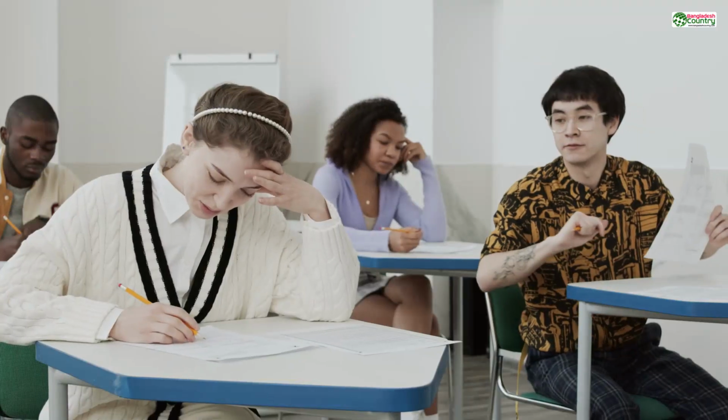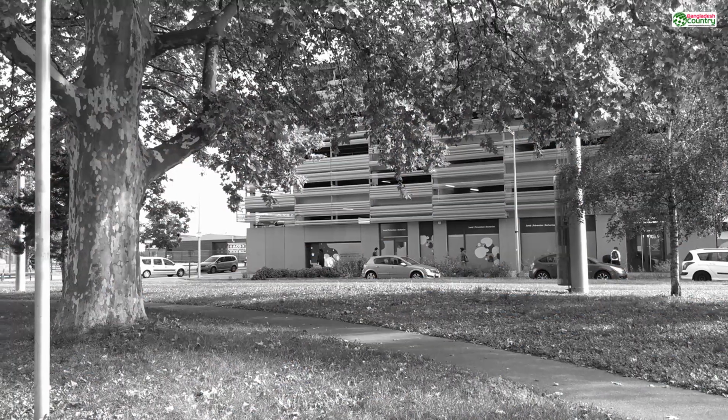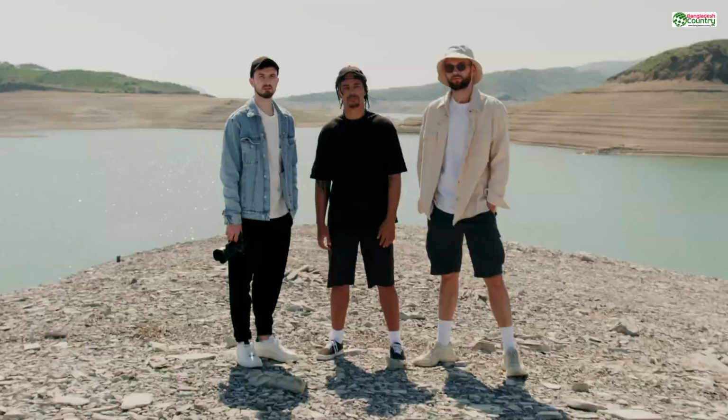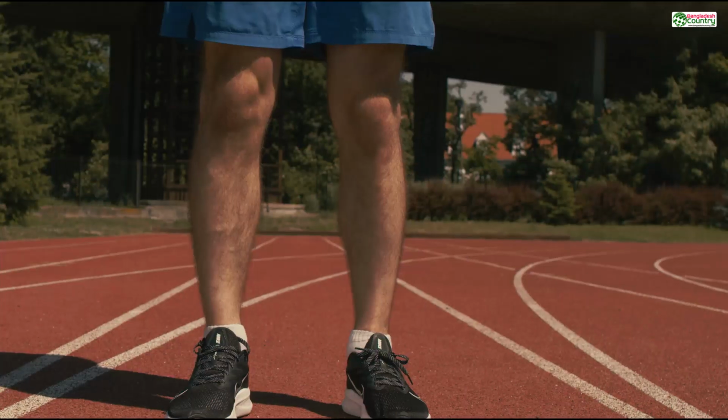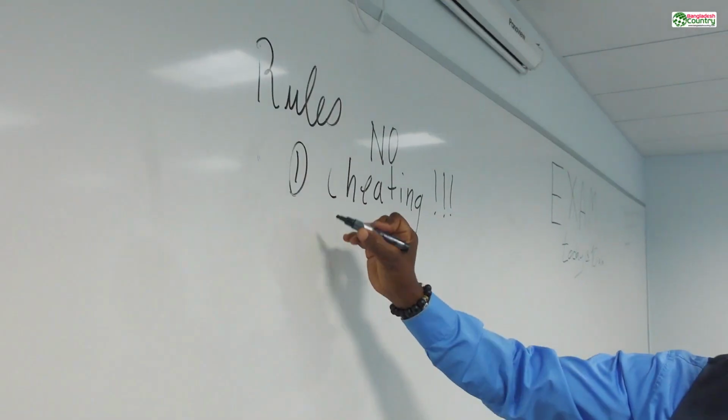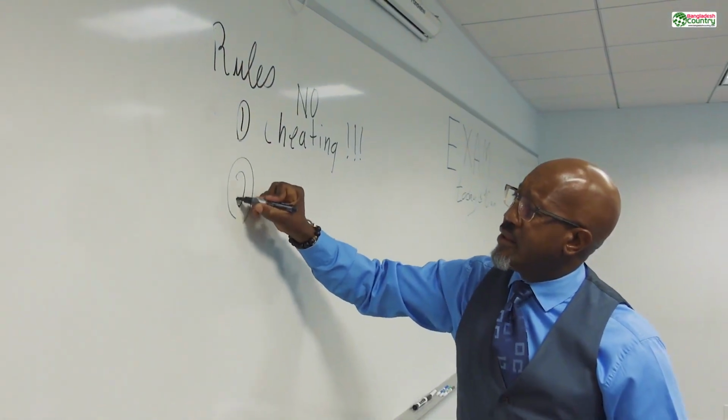They have tested the limits of their materials. They will provide a minimum recommended wall thickness for each one. This is your starting point. My personal rule of thumb is to take their absolute minimum and add 0.5 mm or a full millimeter for safety, especially for larger parts.